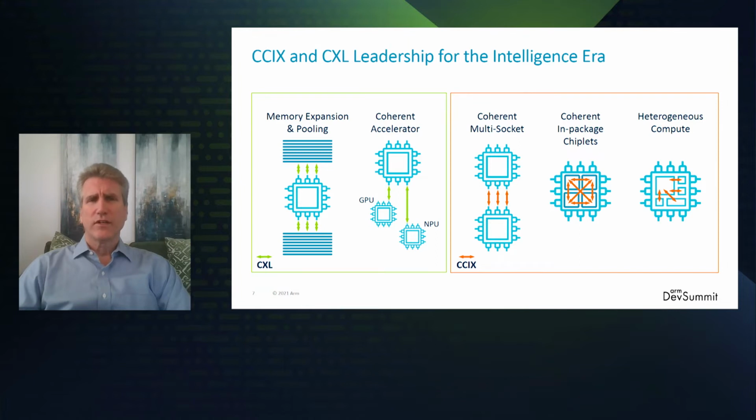Those single mesh configurations on the previous slide can be expanded with CCIX and CXL gateways to connect to other dies or multi-chip modules or some other accelerator or memory expansion modules. Both CCIX and CXL protocol provide multi-chip cache coherency connectivity, but their features and capabilities are different enough to maintain both. CCIX has a rich set of coherency operations that make it better suited for distributed cache Snoop filtering across several identical heterogeneous devices, whereas CXL's host-based coherency policy allows one to make simpler memory expansion models and accelerated devices.